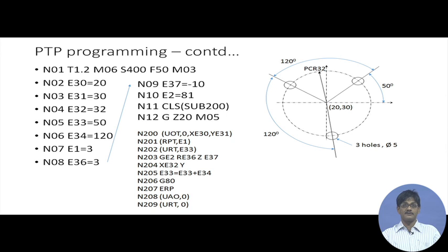Now, that is a bit complex to understand. Let me express it once again. Tool number 1 is being declared, and the offset, that means its length and diameter offsets, will be written in the second line of a file called the offset file. We will take it in more detail, but at this moment we are declaring the tool number and its offset.